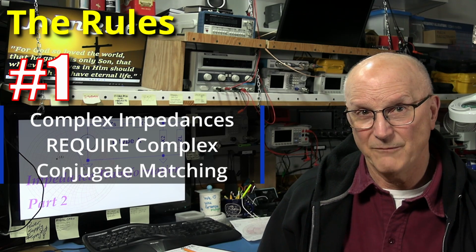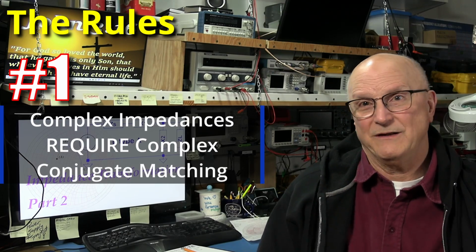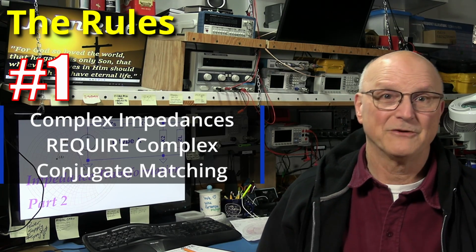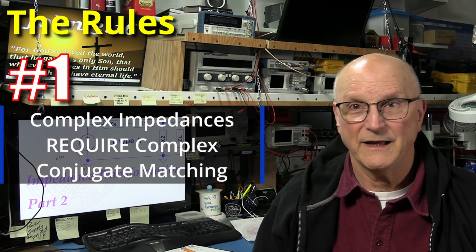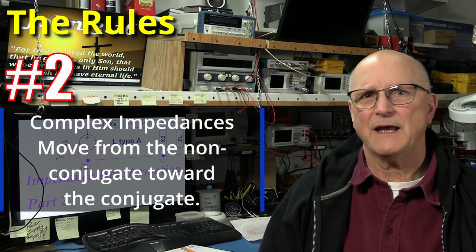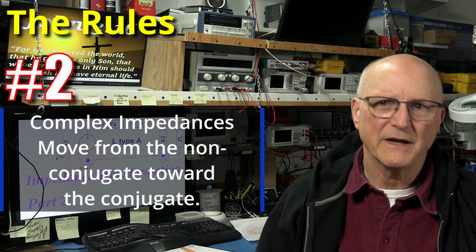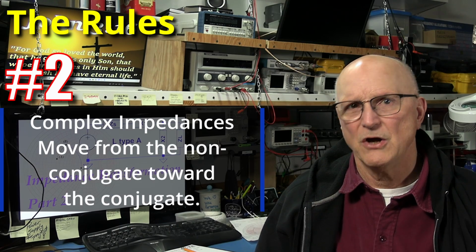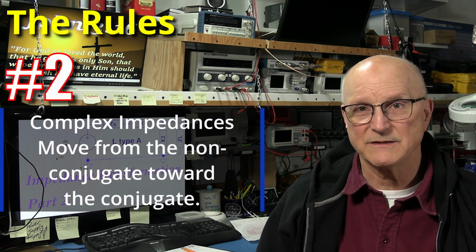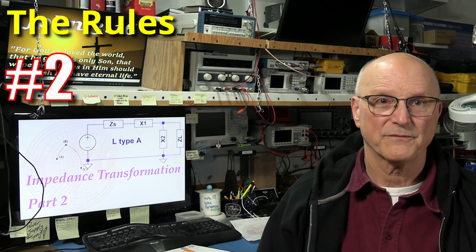If neither of the impedances are complex, then conjugate matching is kind of irrelevant, and direction of travel is equally irrelevant. Rule number 2. In the case of complex impedances, always move from the non-conjugate impedance toward the conjugate impedance. Direction does make a difference.